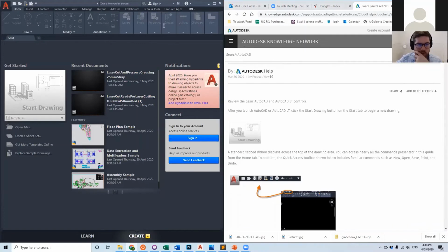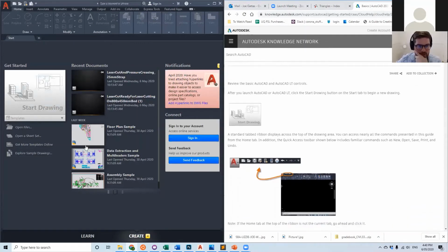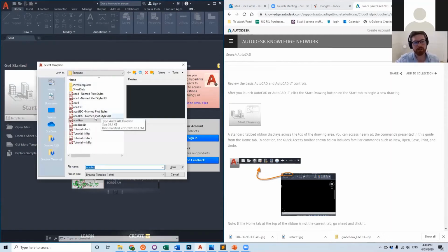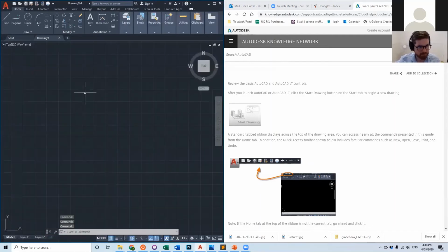All right, so you'll open AutoCAD and you'll get a screen that contains a whole bunch of information here. Just ignore that. Just click New, this top left button up here, same as Microsoft Word. It will ask you to select a template. I'll talk more about that in a moment, but just whatever's fine. And this brings up the base screen. All right, this is you piloting AutoCAD.